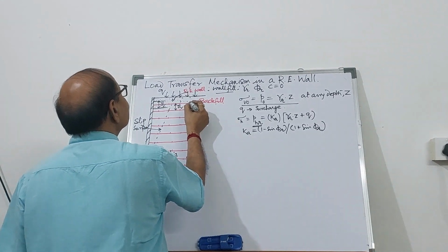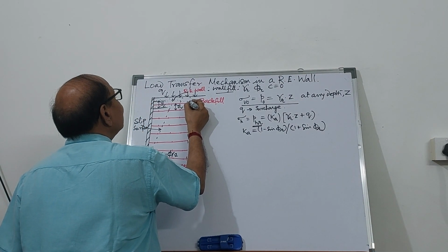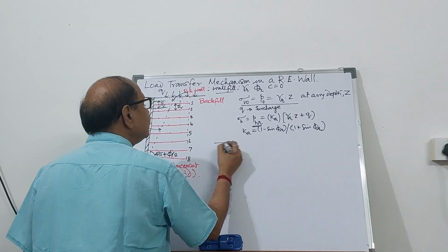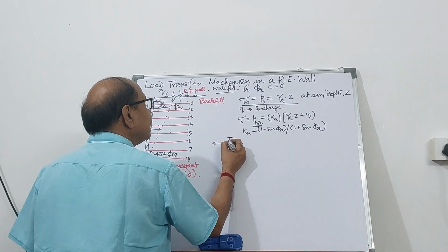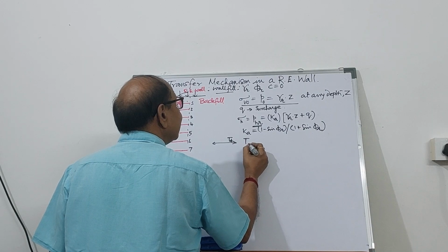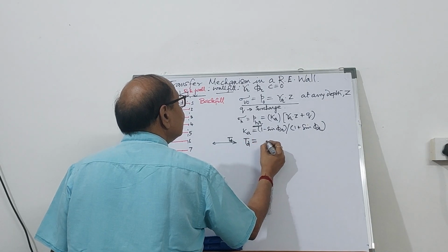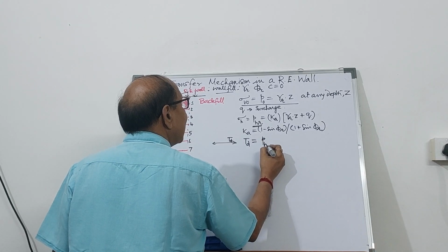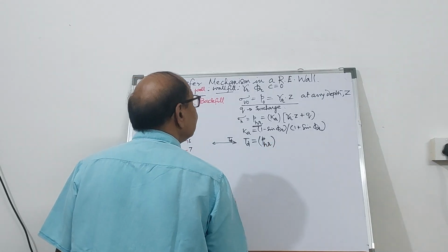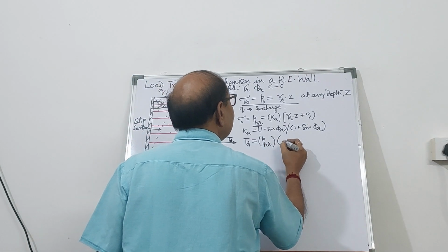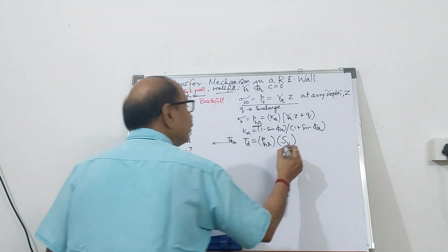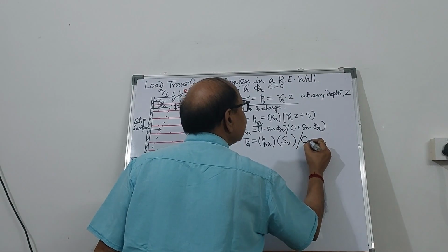So what is the tension that is getting developed over here in the reinforcement? So in the reinforcing element, the tension that is going to get developed, we call it design tension or TD, will be equal to what is the horizontal pressure in the reinforced zone, PHR, multiplied by the vertical spacing, which I have just talked about, divided by a coverage ratio.